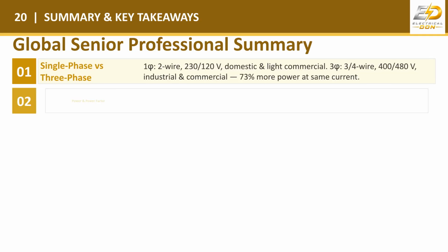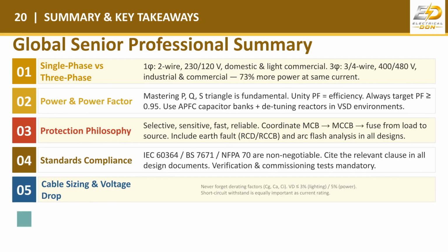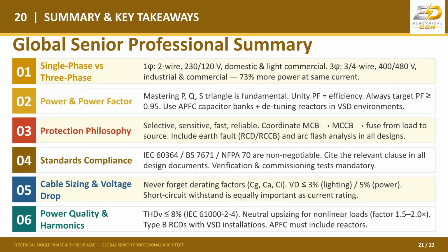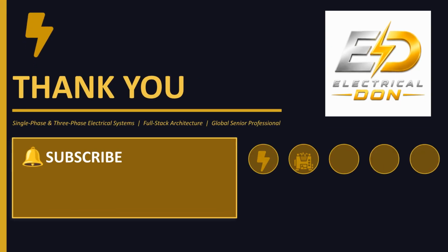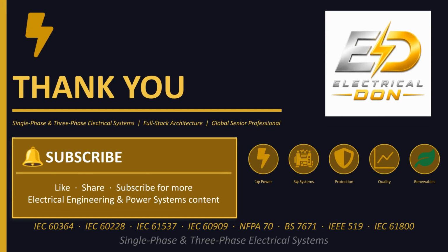In summary, master the fundamentals of single-phase versus three-phase power and the power triangle. Prioritize selective and fast protection, ensure compliance with international standards, and always consider derating factors for cable sizing and quality limits for harmonics. Thank you for viewing this video on single-phase and three-phase electrical systems.